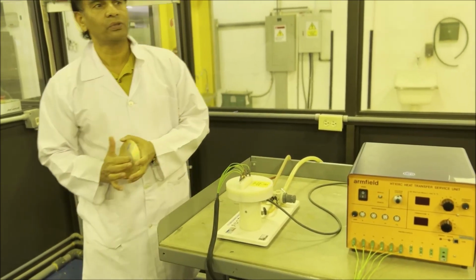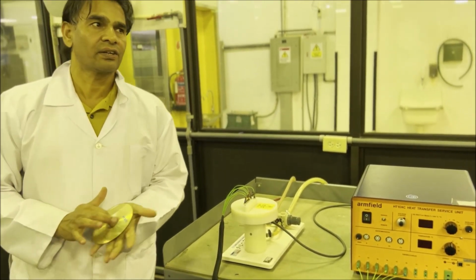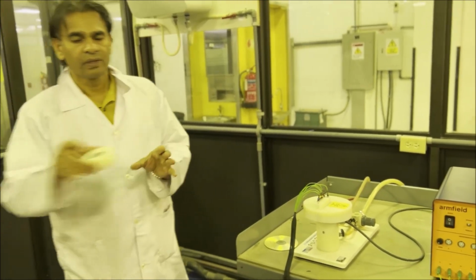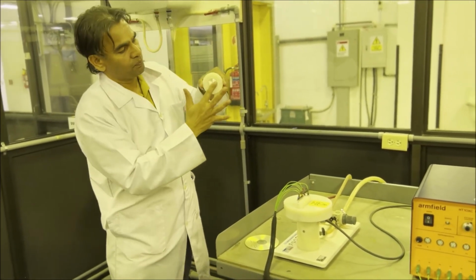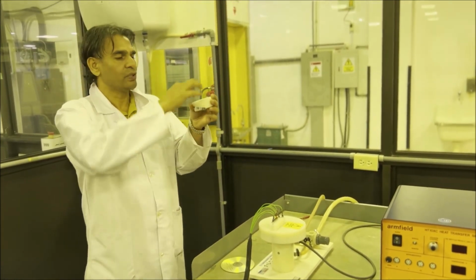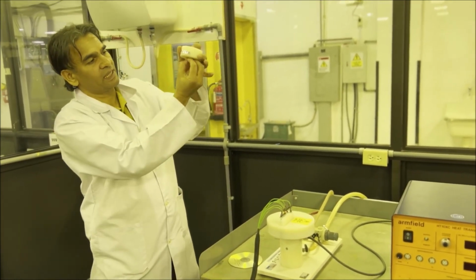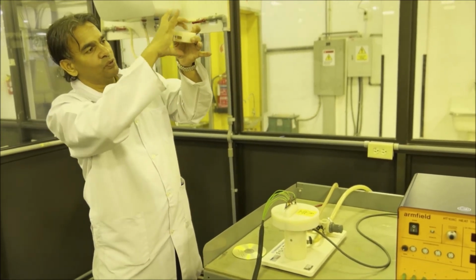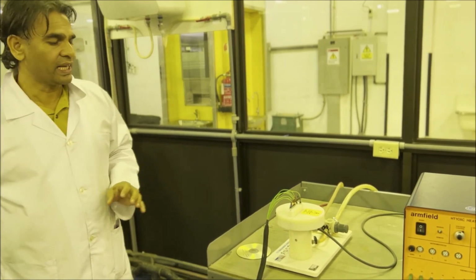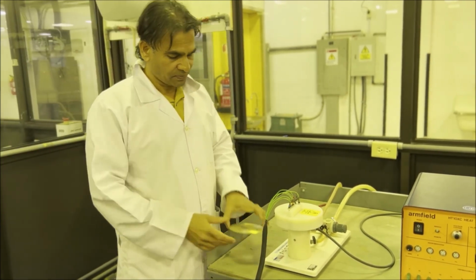Now this week we are going to study radial heat conduction. What is meant by radial? In linear, I told you the heat flow area, pi by 4 d square, remains constant. So heat is flowing from this surface and it is coming out from this surface. During this distance, the area is constant and the heat is also constant.